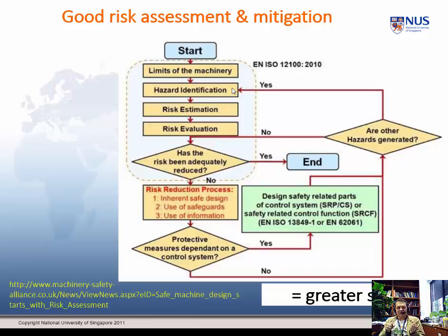If you've got someone there, on the other hand, doing all sorts of things and using this equipment, now we're thinking of machinery on a factory floor, so yeah, think of putting hands into moving parts, think of long hair getting caught, just to visualize it. Only when you've got what people are going to do can you identify hazards.